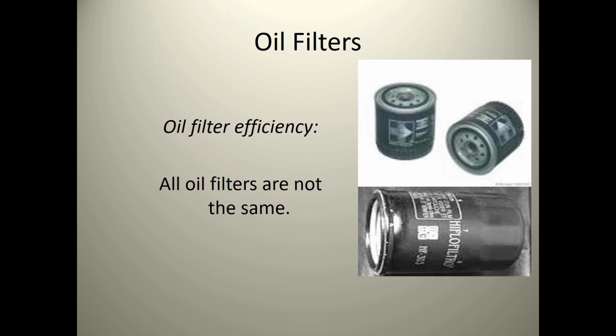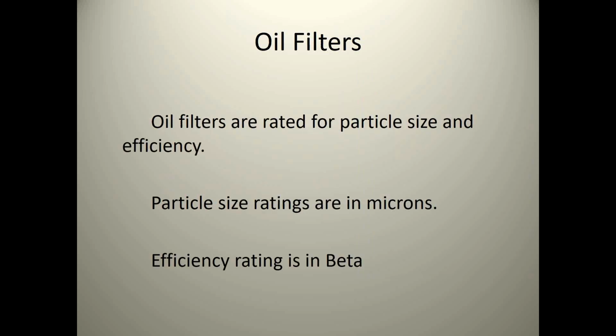But a lot of filter companies that are very popular in the industry, and Parker's a good example, if you have a Parker filter card, or you call Parker and buy filters, and ask them what the beta rating is, they don't beta rate their filters. They're rated for some micron sizes, but they don't have any efficiency rating. So they're not very good filters for what we're trying to do in lubrication excellence. They're all right in a mine to take big particles out, but they're not okay in some critical equipment to get small particles out. So all oil filters are rated for a particle size and for efficiency.